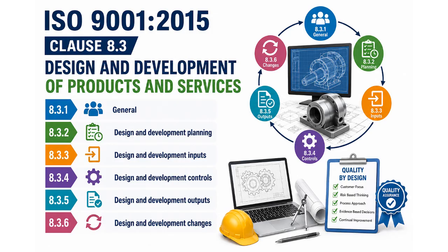Subclause 8.3.2 is design and development planning. This clause basically focuses on design and development planning, ensuring organizations systematically control every stage of the design process. This includes considering the complexity, duration, review stages, verification and validation, responsibilities, required resources, and coordination between all involved parties.